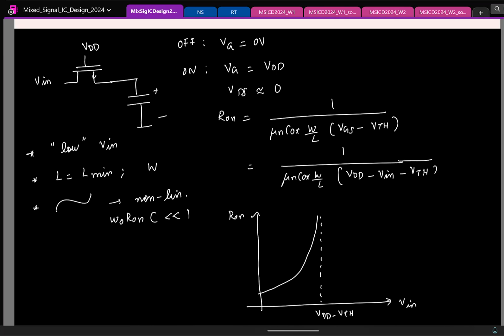So which means, let us say I do 2 experiments. In the first experiment I apply a sinusoid with a frequency omega 1. Second, I apply a sinusoid at a frequency omega 2. Say omega 1 is much smaller than omega 2. I look at the output samples in both cases and look at the output spectrum. In which case do you think the harmonic strength will be higher? Omega 2 or omega 1? Why? As you see, this has to be smaller. If you have a smaller frequency, this is going to be smaller, so obviously it's more linear. Right?